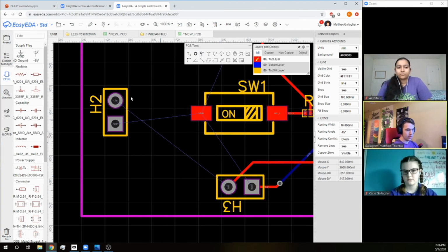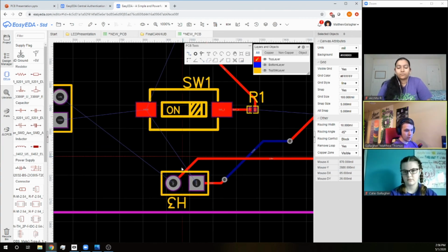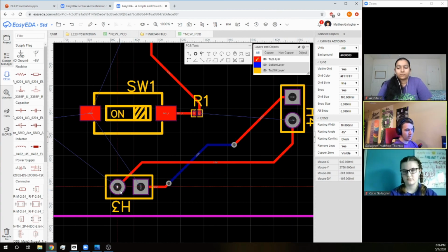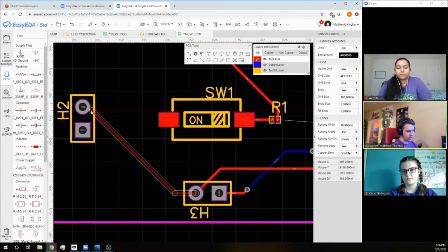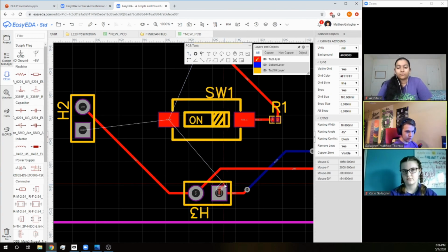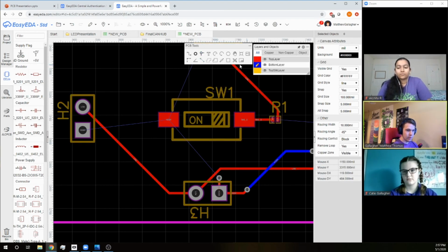I'll go ahead and do one more real quick, and then I think after that you guys should be able to follow the pattern. So since we did low on top, we'll keep that same pattern of doing low on the top, and then we'll bring high over here. We'll put a via on it. We'll go edit the bottom. We'll bring this connection over here.